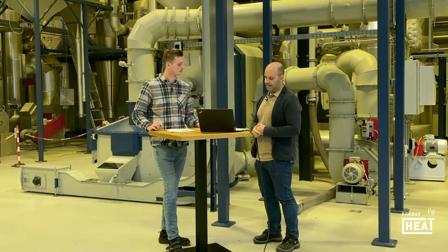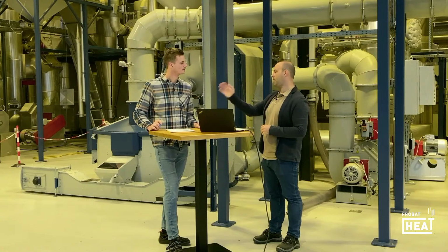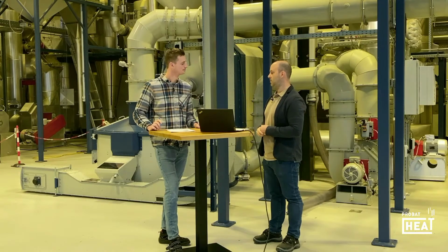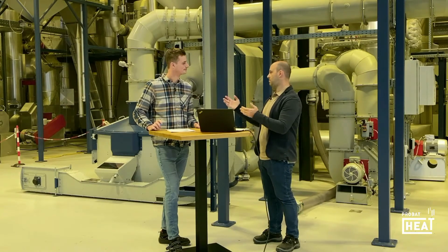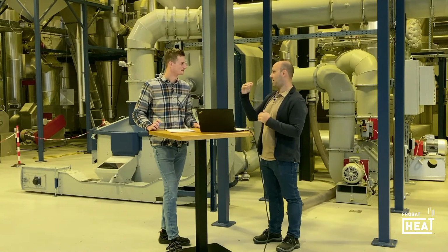That checks for vibration, I guess. Yeah, vibration is then of course vibration. We have implemented a dedicated vibration monitoring at the fan. It's the same: we can measure whether there are any imbalances or something like that, where we can get information that this fan is going to break in the next weeks or hours or something like that.